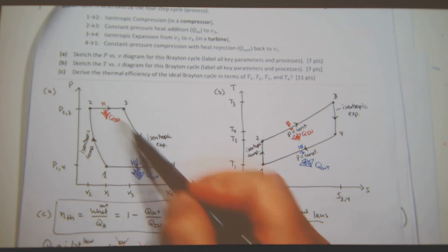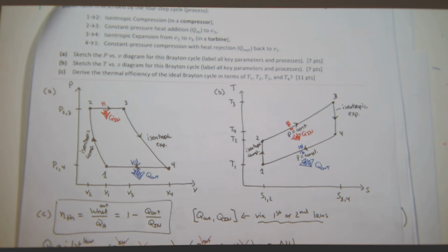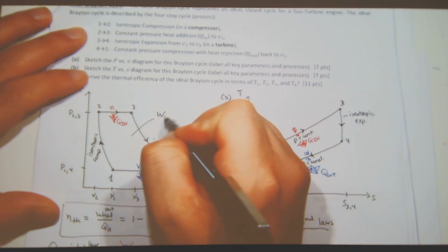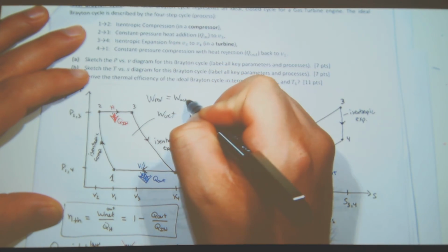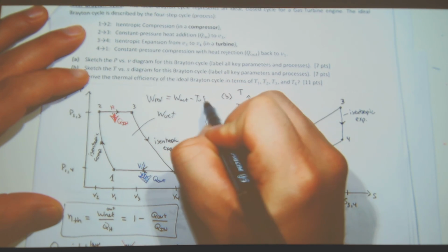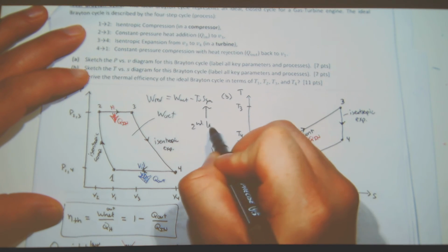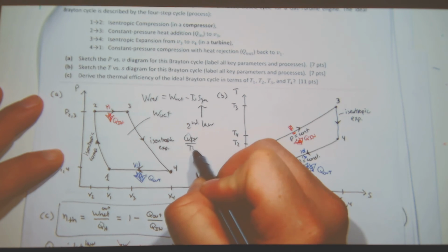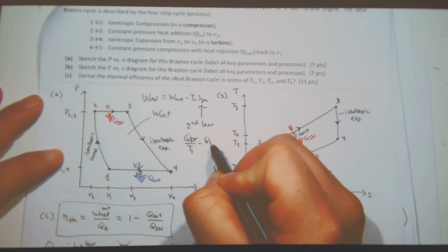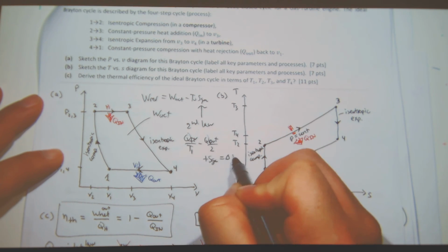And you would have to calculate the entire actual work, which is the area under the curve. So this is work actual, right? And then my work reversible would equal my work actual, this is power producing, minus T0 S gen. And then I would get S gen from the second law. In my second law, I would have Q in over T1 minus Q out over T2 plus S gen equals delta S in my system.